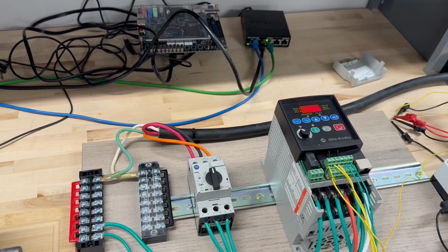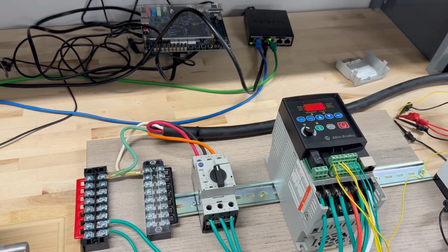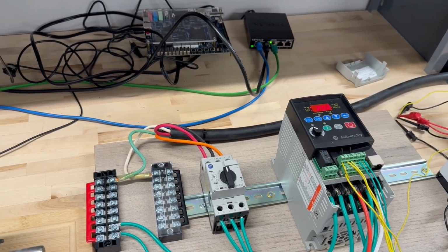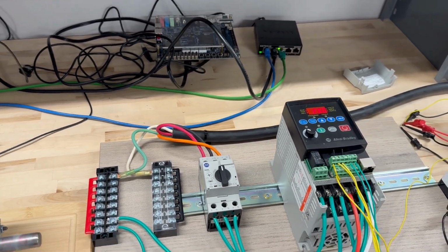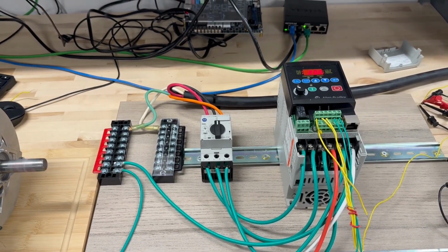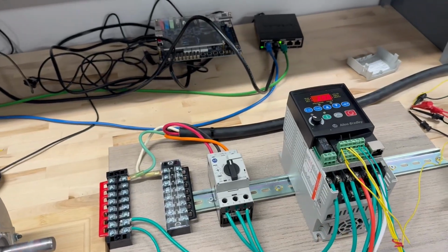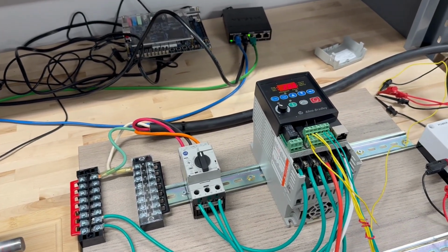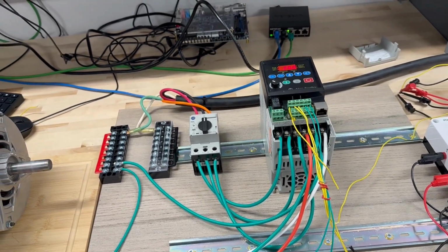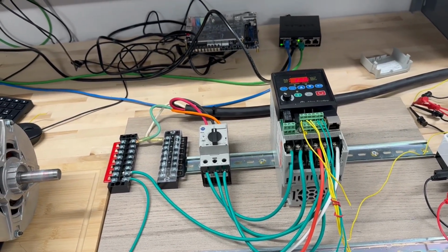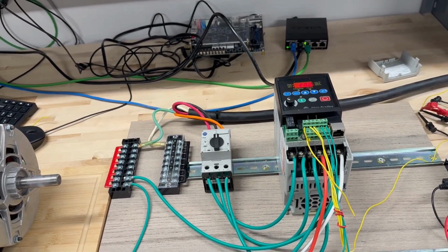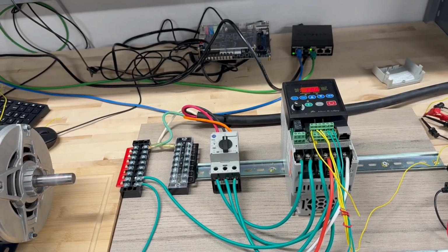And for acceleration and deceleration 1, we could use parameter P39, and P40 is for acceleration time 1 and deceleration time. We don't want to check all of them, since all are the same, so let's just check one of them. Let's change acceleration time 2, which happens whenever the switch is on 0, 1 and 1, 1.